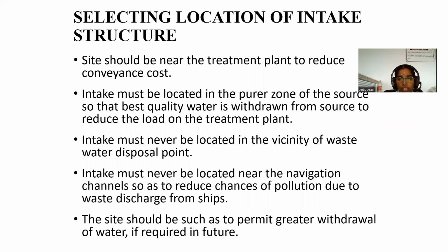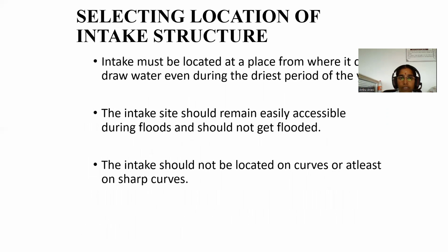Intake must never be located in the vicinity of the wastewater disposal point. Intake must never be located near the navigation channels so as to reduce chances of pollution due to waste discharge from ships. The site should be such as to permit greater withdrawal of water if required in future.